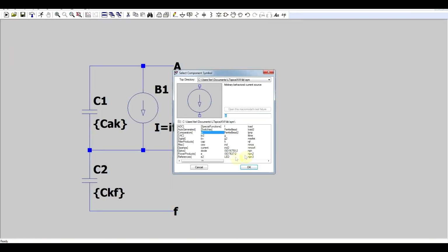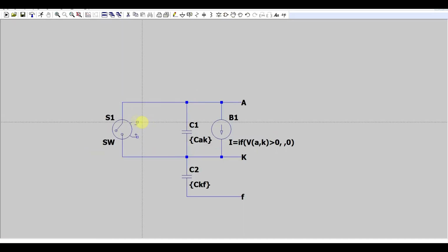Now in vacuum tube diodes, this breakdown voltage mainly results in arcing. So you'll get an electrical arc between the two terminals. So you either have no current or you have a lot of current going. And the easiest way to model this would be using a switch. So what I'll be adding here is a simple switch that will check the voltage between the cathode and the anode. And based on the parameters, I can set it to turn on when a certain negative voltage is reached.